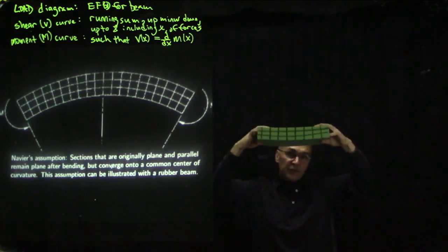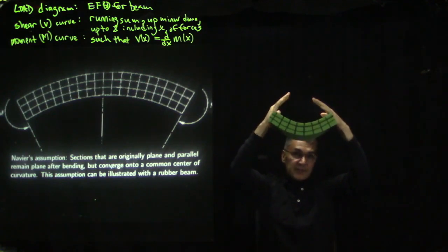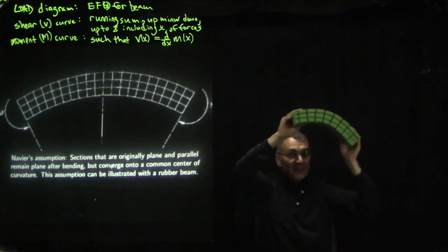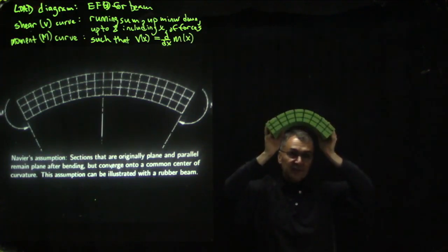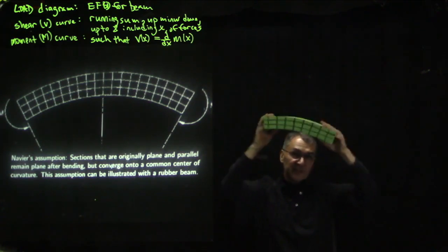And then if I were to do something similar with a beam that is simply supported, so it's supported on the ends and there's a load in the middle, then you would see the opposite is true, so the top is in compression and the bottom is in tension. We draw pictures that look more like this shape. You could kind of imagine this for a cantilever. This shape where it's frowning but both sides are sagging downward seems a little bit contrived, but it turns out to be a nice shape for drawing diagrams.